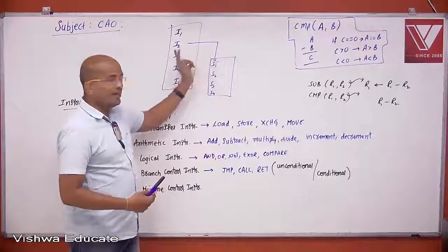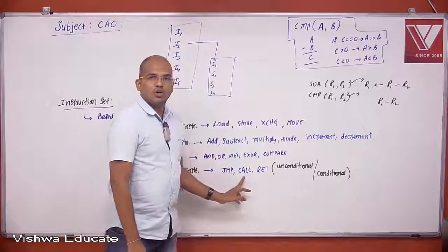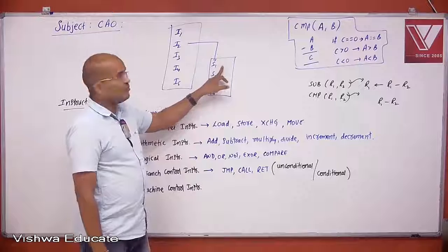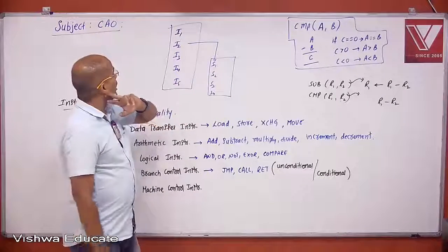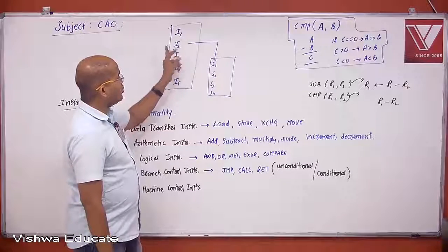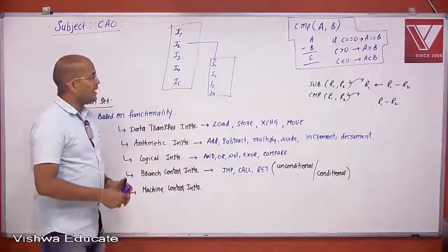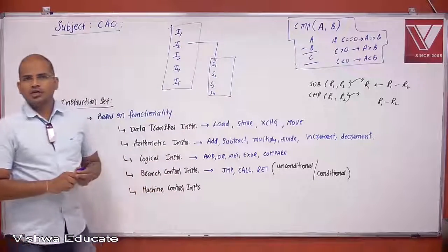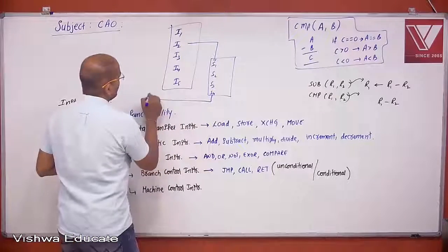This happens internally in assembly coding by an instruction called call. You call this subroutine from the main routine. You observe that the control is going from I2 to S1, not in sequence, so this is called branching. Once the branching part is done, you should go back to I3.